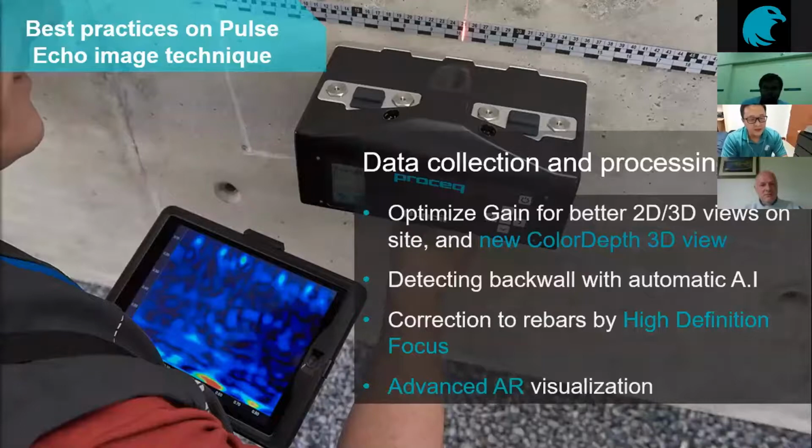There are a few gain functions. I may not give more details over here. The first gain function we call analog gain, also called total gain. It means when you enlarge the gain, it will go up and down all along the transmission line. All the A-scans will be amplified, right? We also have a TGC function. TGC amplifies the further field, and you can look at the further field object as clearly as the near field.